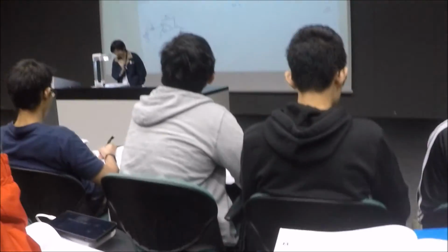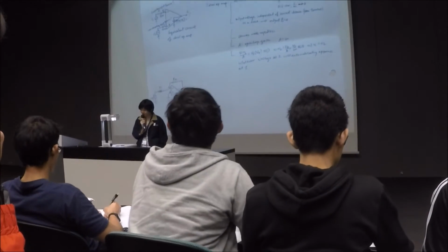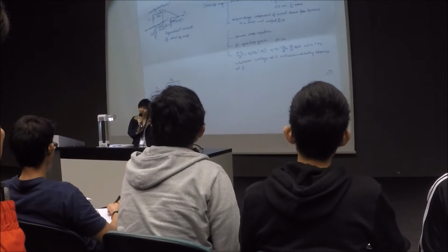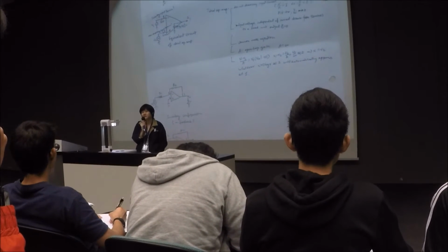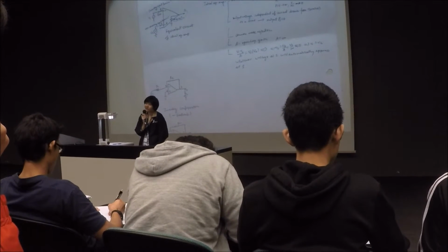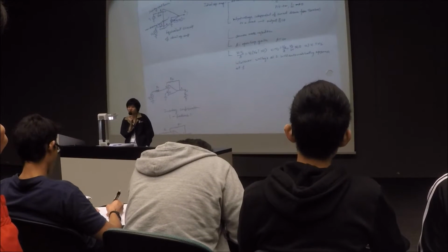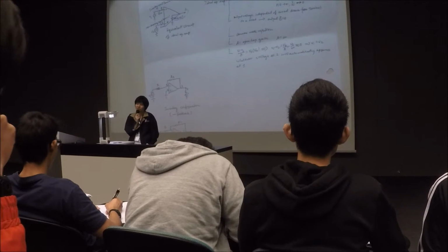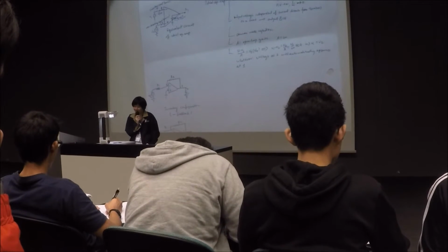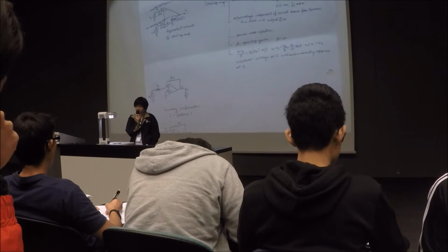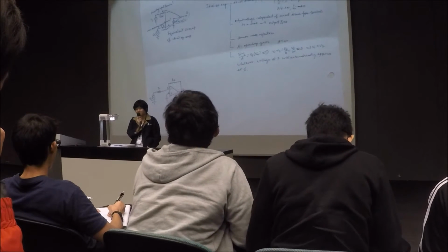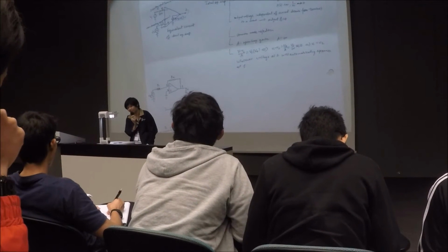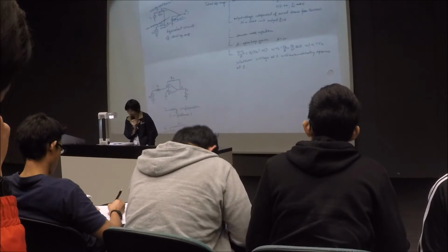Alright. And there's another important assumption, the input impedance, okay? Looking at the op amp from the input, the input impedance is infinite. So there's no current drawn into terminal 1 and terminal 2. This is for the ideal case, of course. It is assumed to be infinitely big input impedance. Alright. But usually the input impedance is at the mega ohm level, so it is considered very big.